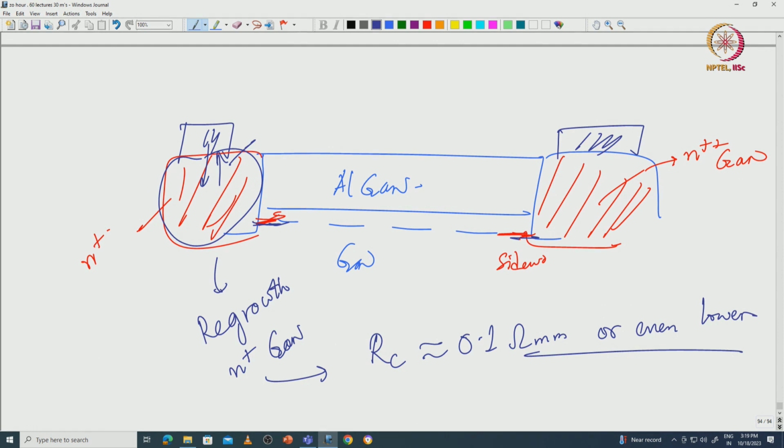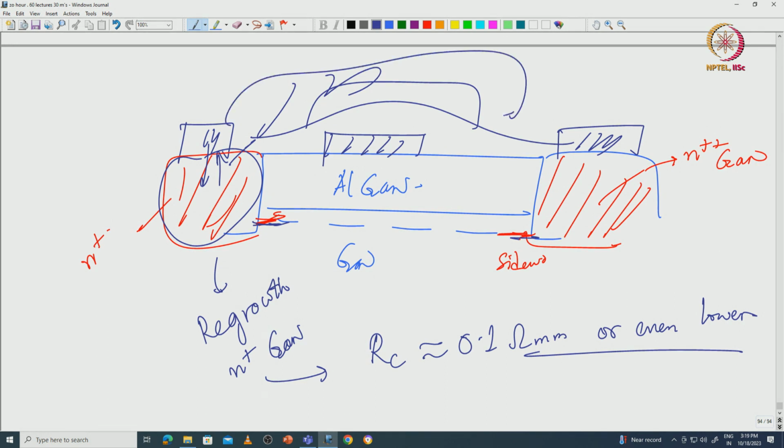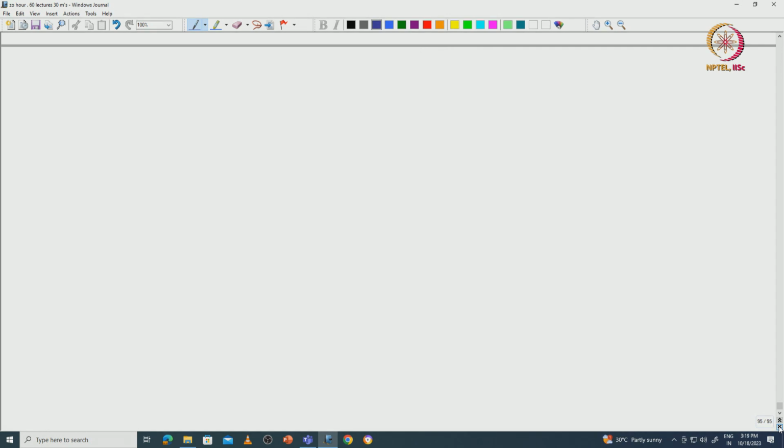So, for instance, contact resistance reduction itself could be a very process intensive and effort intensive thing, and then you have gate, then you have passivation, then you have field plate, then you have another passivation, there is another field plate, there are many process steps. So, it is a very complicated and expensive, resource intensive development that people have to undertake, and you have to understand the physics as well as the process concerns. Now, after this is done, it is not so simple. You have to measure and characterize the device, that is a different ball game.